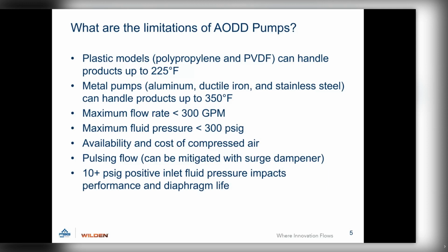And you understand how the pump works. It's got the 4 valve balls in each of the 4 quadrants, and it works with the diaphragm membrane pushing that product in and out. So why is that important on the diaphragm pump? Well, if you're pumping something like a yogurt with fruit on the bottom, you want to keep the fruit intact in that yogurt so that it comes out tasting and feeling like fruit. If you're using a diaphragm pump in the wine industry, you don't want the peelings or the grapes to go through a gear and get mashed and change the flavor profile of it.